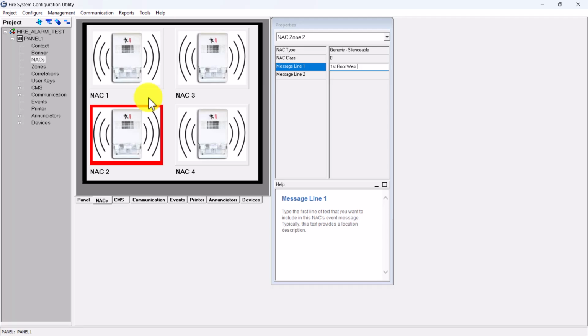So on a point type for the control relay, you have two different types of point types, relay non-silenceable and non-silenceable latched. Now, what this means is when a fire alarm control panel resets, if you have it on non-silenceable, the relay will automatically go from closed to open, or go back to its normal state once the system resets. If you have it on latched, the relay will stay engaged until you hit a secondary button, like a fan restart button, in order to release the relays to start the fans or whatever operation you have to do after that. And relay silence, I have no idea what that is.